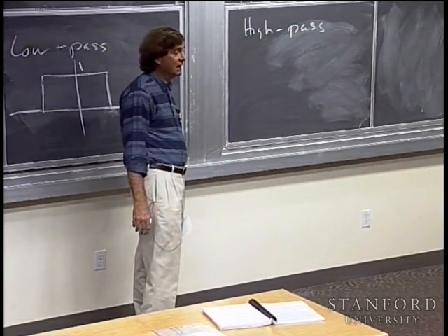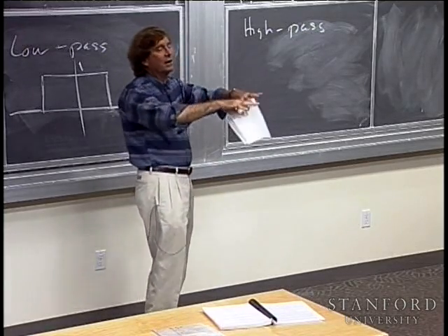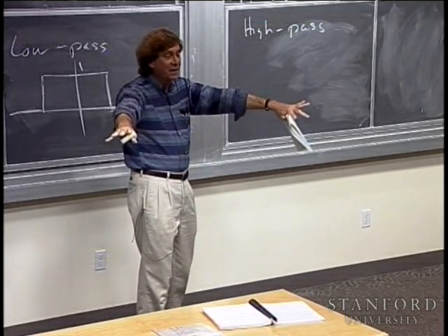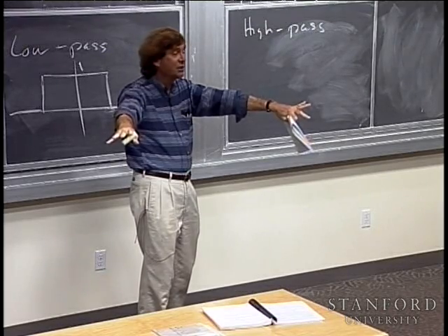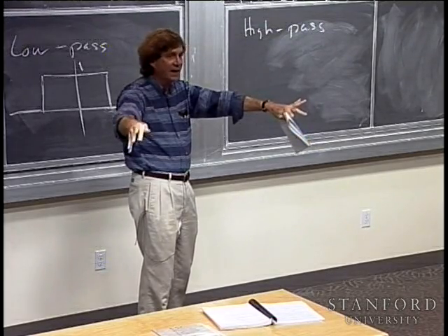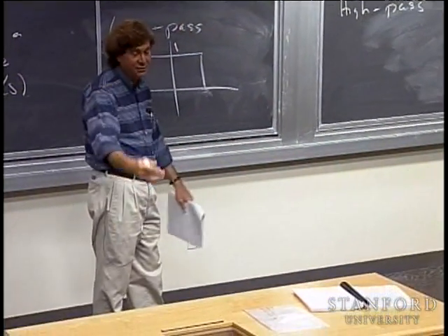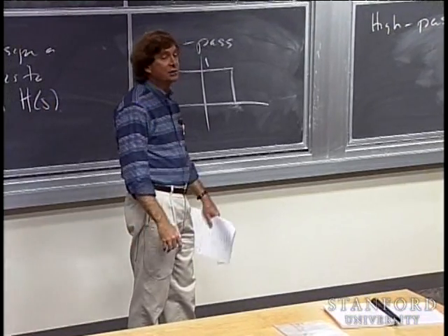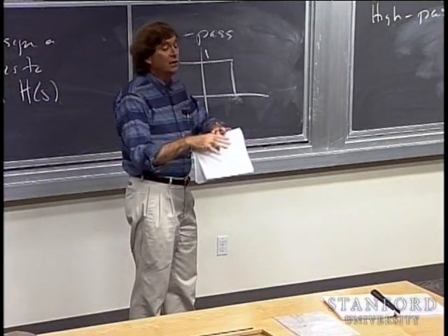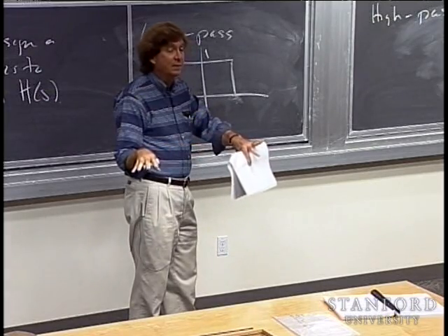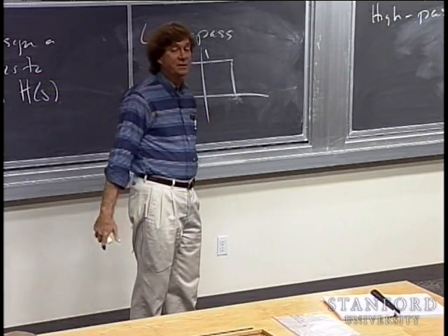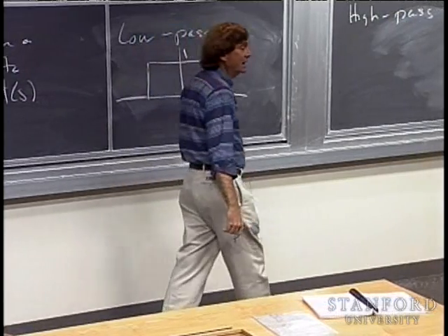Whereas a placid scene has not much variation in the shading, not much variation in the intensity. An edge is a very rapid variation in intensity, say from black to white. Whereas just the ordinary scene, this desk or something like that, might not have much variation. That would typically be low frequency. You want to kill those off and then emphasize only the high frequencies. That would detect the edges in an image.